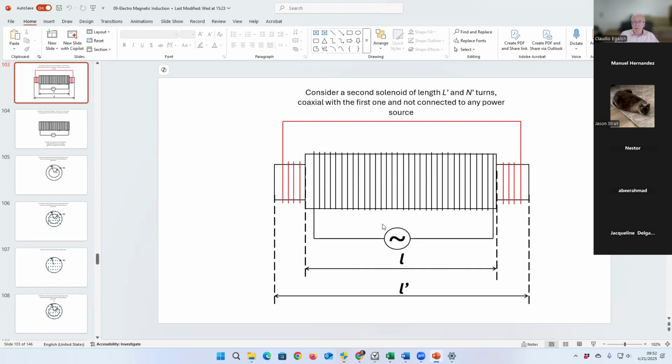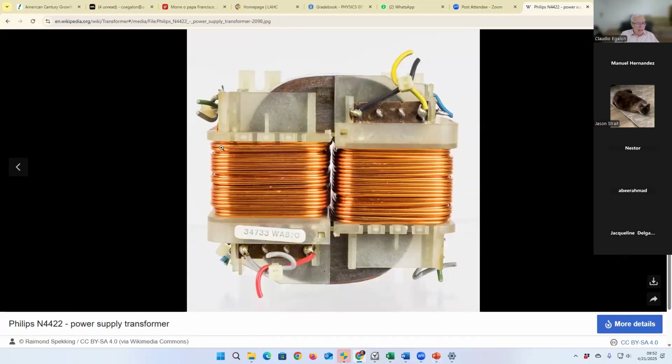And people discovered that this configuration is rather inconvenient, because you have to insert one solenoid inside the other one. But people discovered a simpler and very convenient way as well. Instead of inserting one solenoid in the other, we get two coils, two solenoids, of the same size, though not the same number of turns, and we insert this metallic bar, or rather a metallic donut, inside both solenoids.